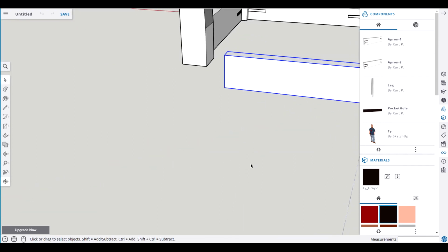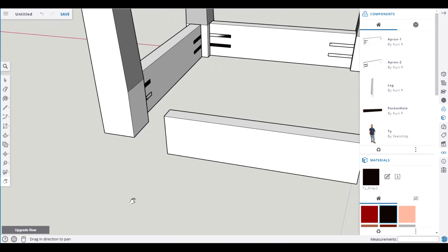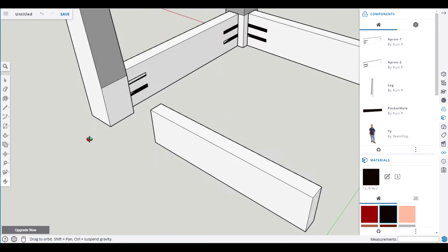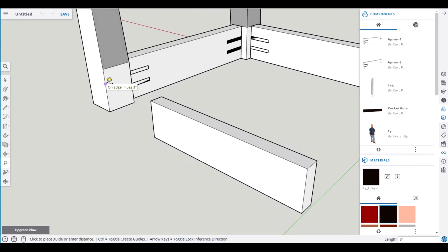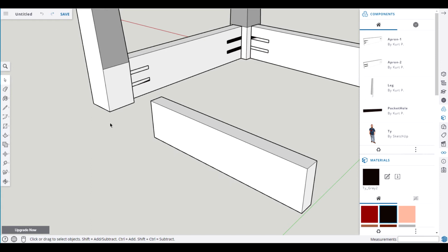We can see that we're way off. Free space to unselect, bring the hand in, and with the H key, and now we're going to do a guide here. We're going to have to move this a little bit, and let's anywhere on that line you see on edge, type in 3, enter, and that did not work. Control Z and Control Z. Nope. Let's undo, space bar, undo. Now what we have here, let's try it again. We're going to do the tape tool, grab here, move it over, 3, enter.